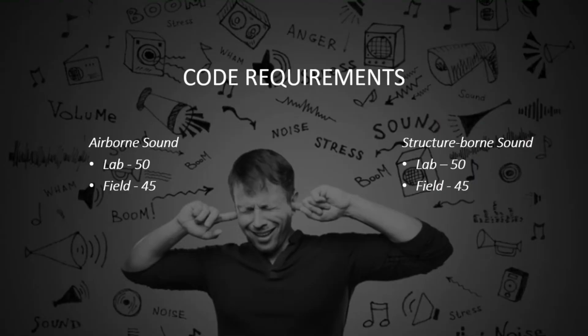So code requirements, right? In the beginning, we talked about the codes, but what are the code requirements? This is for multifamily housing from the International Building Code. For airborne sound, if it's a laboratory measurement, it's a minimum of 50, so that would be an STC 50. And in the field, it's a minimum of 45. Now, until the latest code cycle, they didn't actually specify which one of those metrics you're supposed to use for a field measurement. In the latest one, I believe it's specified as NIC for airborne sound.